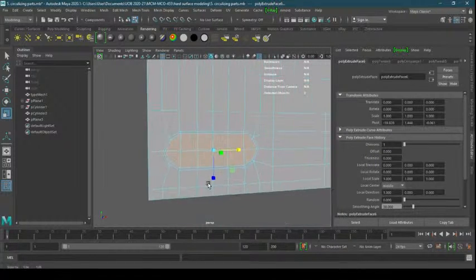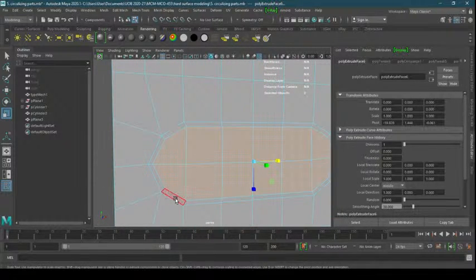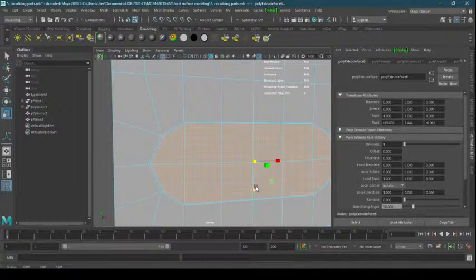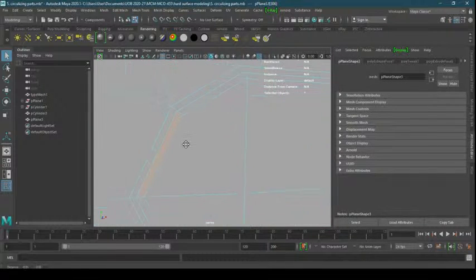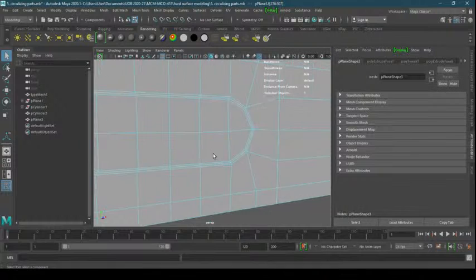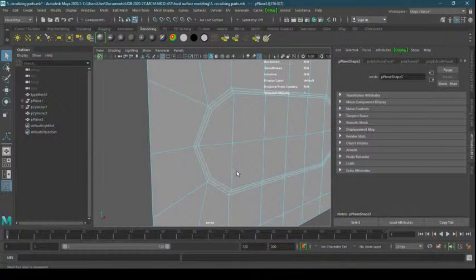And then what I can do here is that instead of doing one extrude, I will do two tiny extrudes, one here, fix this, and then again one more, and fix this, just like this. Press Q to select these faces. Double click here, select this one with the shift key, then double click here, so they all will be selected at once here.